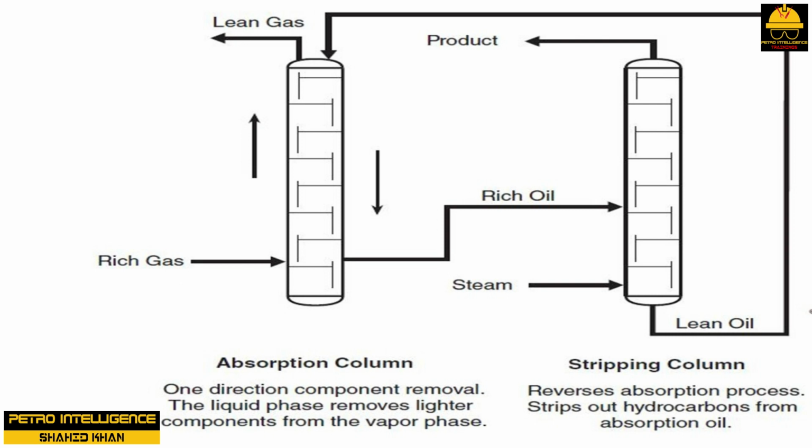Absorption columns. An absorption column is a device used to remove selected components from a gas stream by contacting it with a gas or liquid. Absorption can roughly be compared to fractionation. A typical gas absorber is a plate or packed distillation column that provides intimate contact between raw natural gas and an absorption medium. Absorption columns work differently than typical fractionators because during the process the vapor and liquid do not vaporize to any degree. Product exchange takes place in one direction, vapor phase to liquid phase.